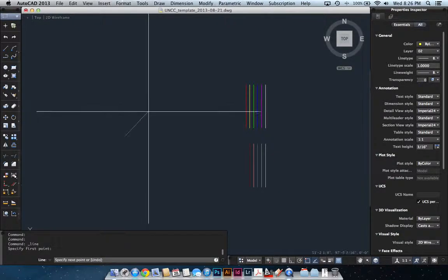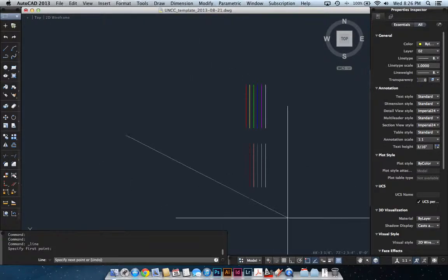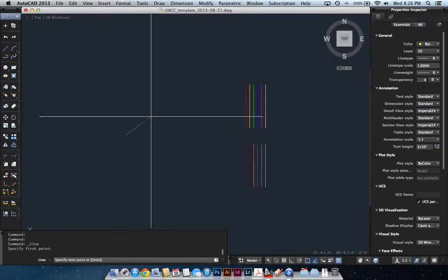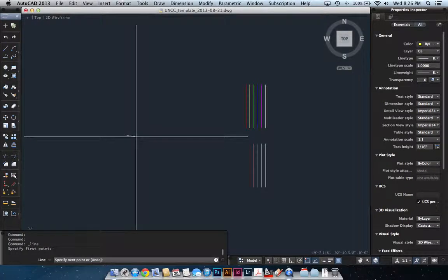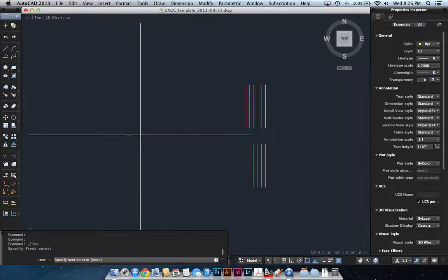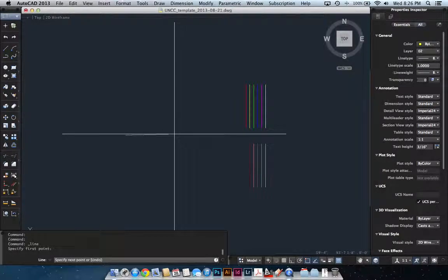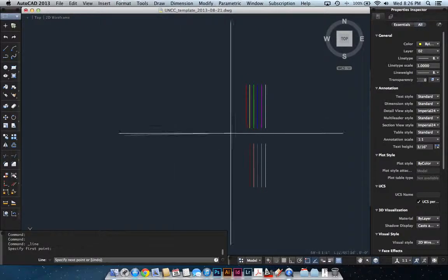But if I draw this, you'll notice I'm just drawing in space. The coordinates are appearing down in the bottom right of the screen, but it really doesn't help you much for the distances, especially if you're trying to trace something or figure out a relative dimension. You have two options to get a dimension. One is you actually type it in via the coordinates with the @ as we talked about in the earlier tutorial, or you actually turn on the ortho